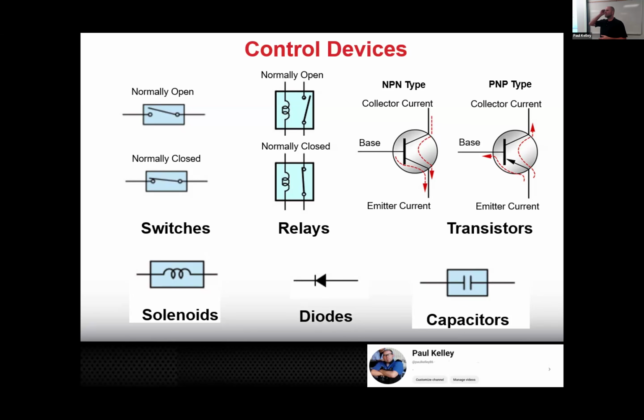But if for some reason maybe the system is overcharged, or maybe there's some massive restriction in the piping or something, the high side pressure will go so high, the excessive pressure will actually open a normally closed switch, and when it opens it, it interrupts the power going to the compressor and disables the AC. So that's an example of a normally closed switch on a vehicle that's there for safety purposes, right?